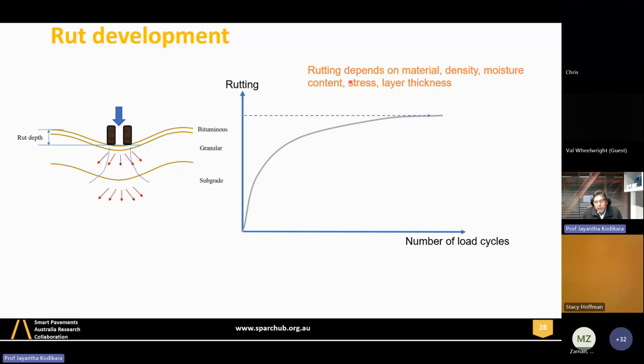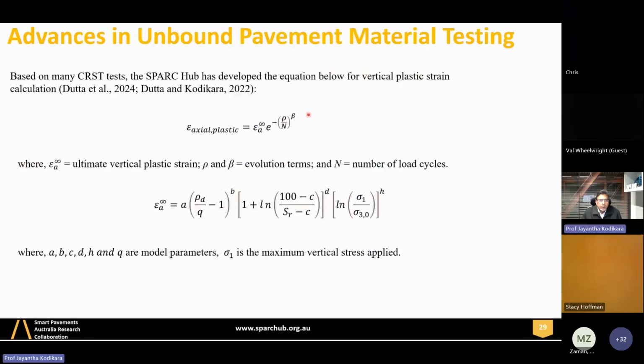Again, we are simplifying, decoupling plastic effects from elastic for stress calculation, but that is a simplification that needs to be done. Otherwise, we will not get a practical solution. Layer thickness is a primary pavement parameter that we design. So these are some of the approaches for design.